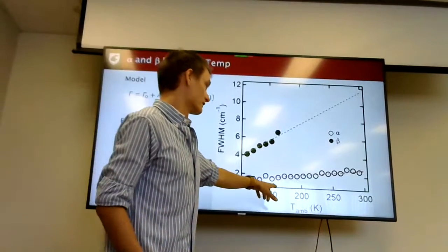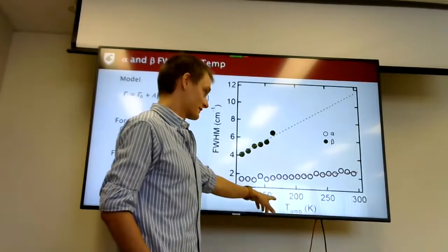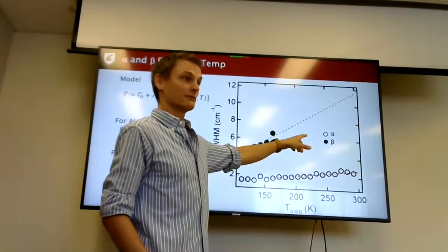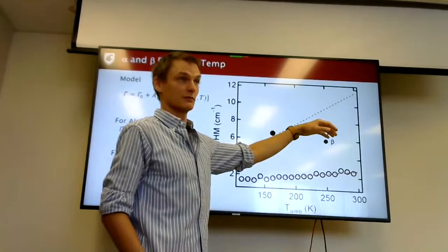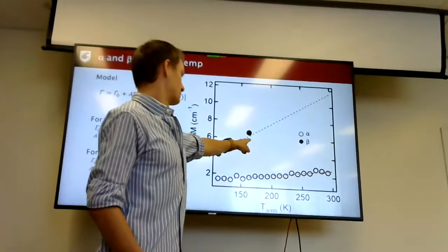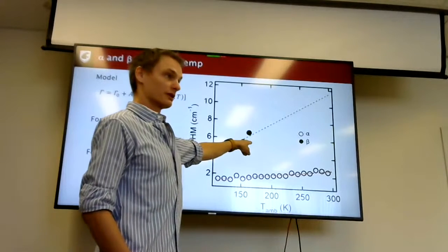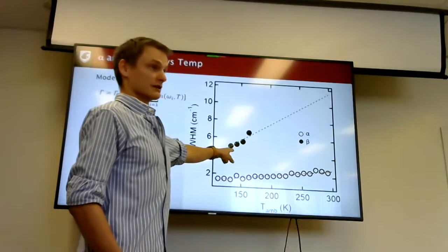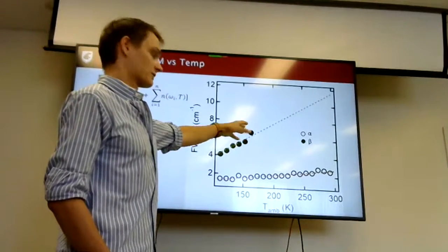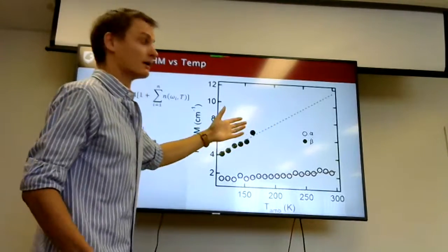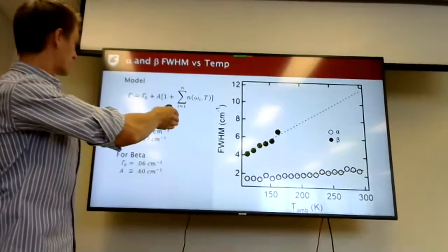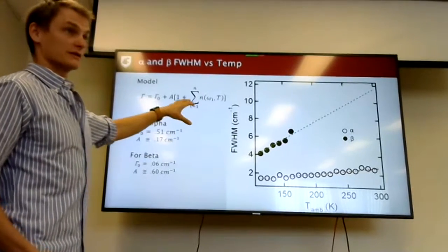And we'll note that even with all this clever nonsense, the beta phase is not extractable beyond a certain point. These last 3 peaks you only get with all the clever stuff. The first 3 are easy to fit. So without those next 3, you couldn't draw a trend line and figure out what's going on. But now we have the full width half maximum, and we can determine what that means for this crystal.